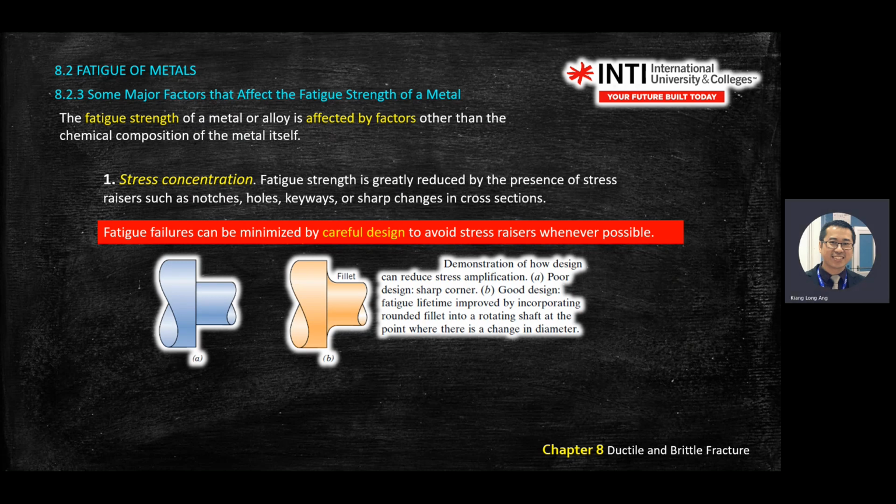Okay, so this one you should be able to observe from your experiment. Here again, first avoid stress concentration. Avoid stress raisers in your design. That's why nowadays, most of the consumer products, we like to have a round surface, or round fillet corner.